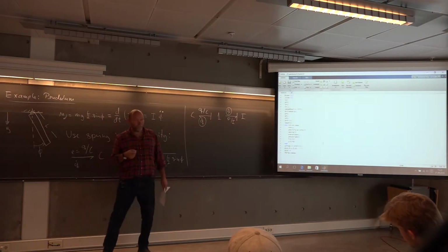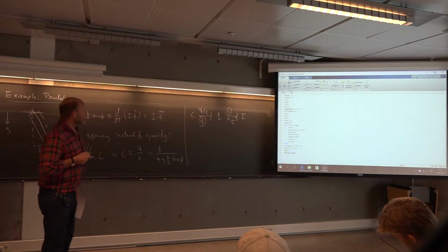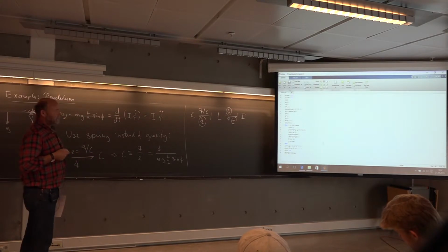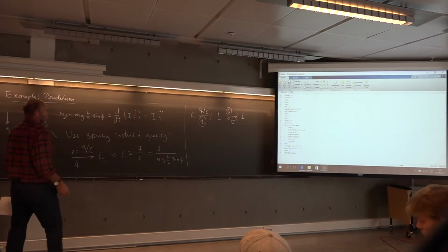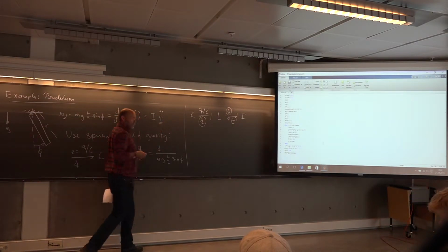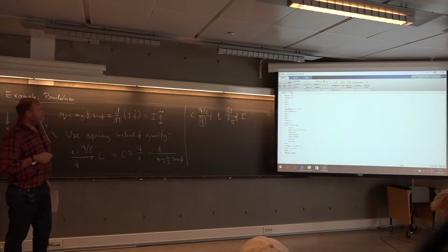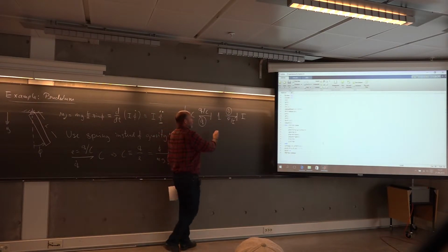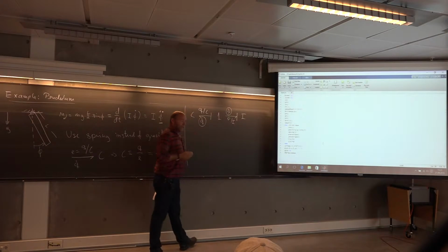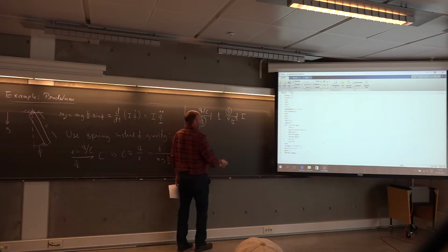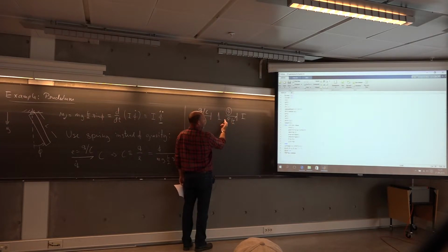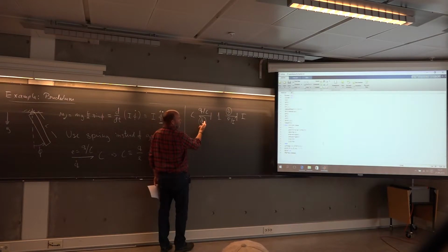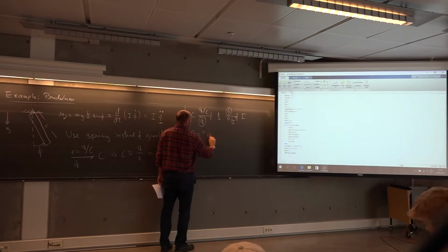What are our differential equations here? Well, it's a second order system, and of course it is. We know that already, double derivative. So now we don't see a double derivative here, of course not, but we have two first order differential equations. First of all, a one junction, that is a common flow. And what is the flow? It's P over I, where we are missing the causal stroke. The I element is in charge. Hence, the flow has to be P over I. Q dot must then be P divided by I. So that's one equation.